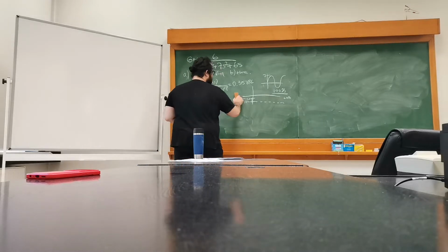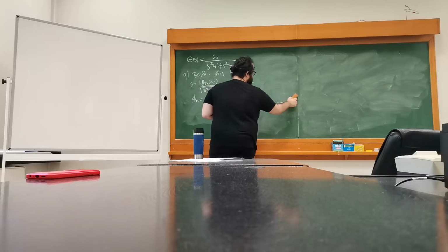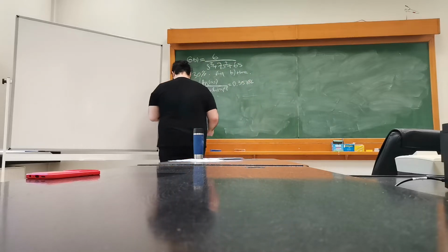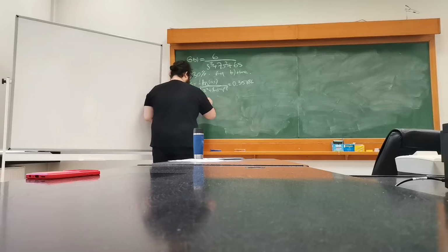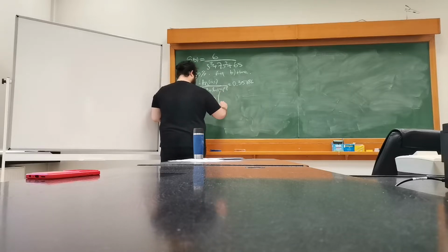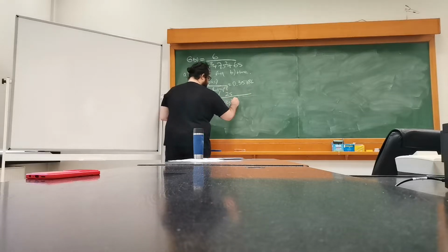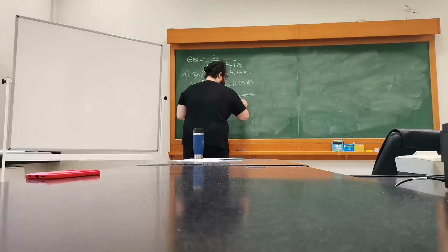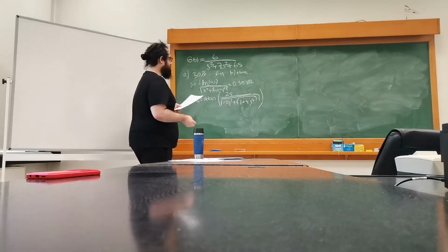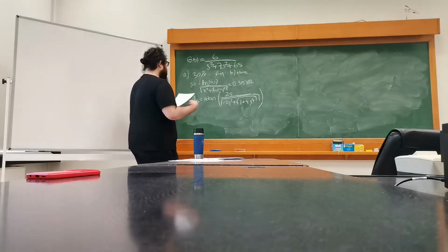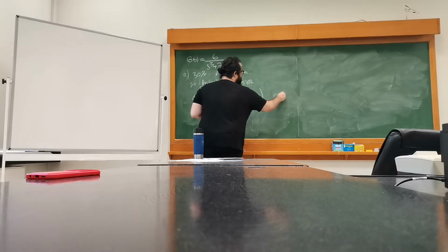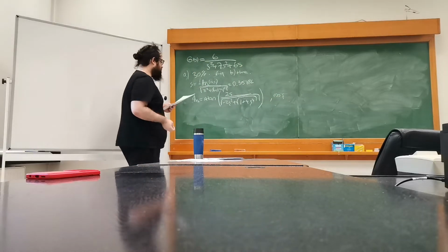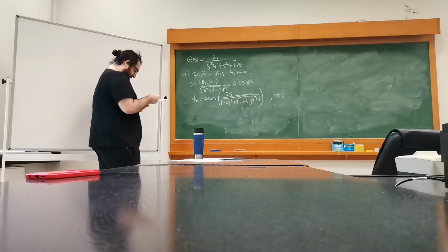One of them is the zeta and phase margin relation, which is arctan of 2 zeta divided by minus 2 zeta squared plus the square root of 1 plus 4 zeta to the power of 4. Or to some extent we can use 100 times zeta. Either of them can be used.